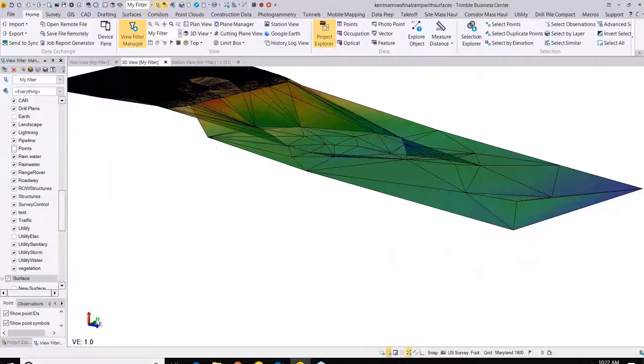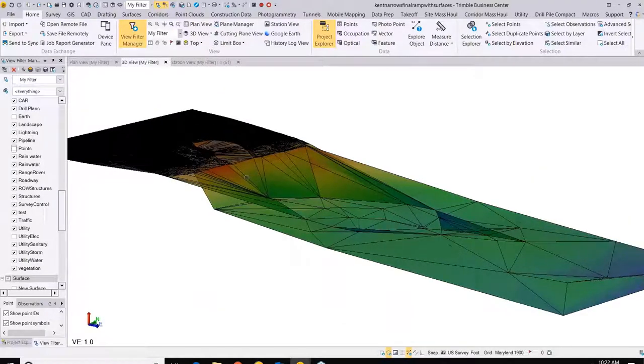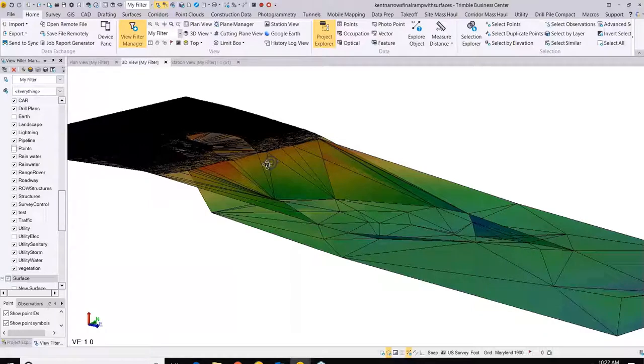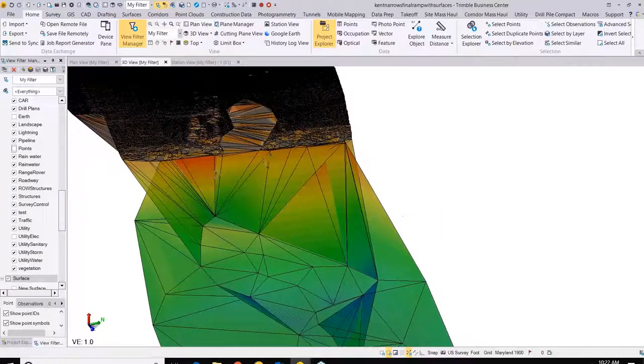And Joe, are there any questions so far about how we've gotten to here? Are we okay so far? Yeah, we've got one from Mark concerning the tidal ranges. He was asking about how the Sonarmite was logging the data. If you logged the coordinates as RTK coordinates, would this not automatically give you a true bed reading as the tide rose or lowered?